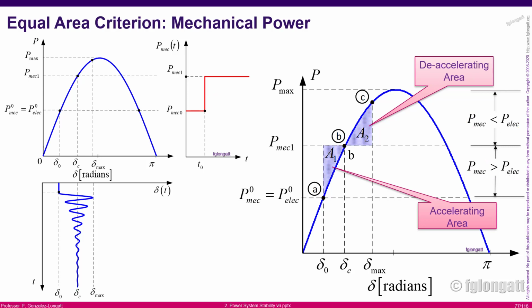When there is this disturbance inside the power system, this big change in mechanical power, the machine will try to move from A to B. But the movement from A to B is not like that in an electromechanical system. In reality, the system will go to B, C, then go a bit here, then here, then here, oscillate around B, and then reach the point B.